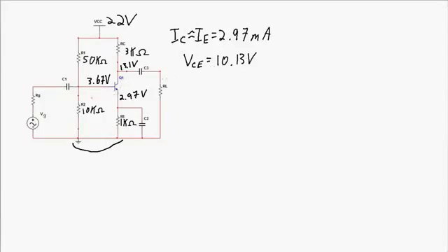This transistor is biased to the active region, and we can add an AC signal, apply it here at the base. This is our input signal. The circuit's going to act like an amplifier and give us an output signal that's going to be applied across the load here. And now our circuit can do something useful. It can be an amplifier.